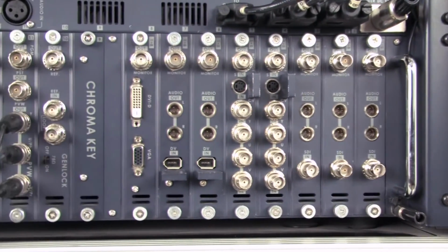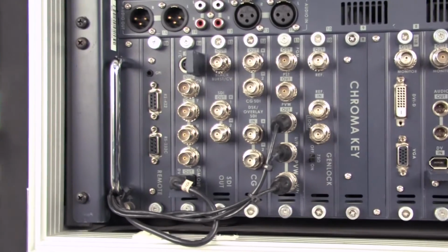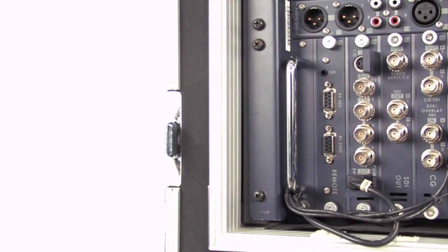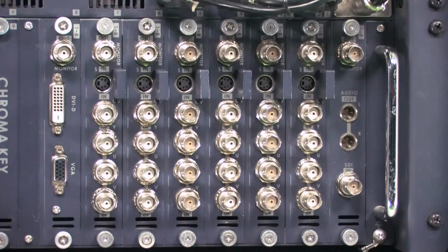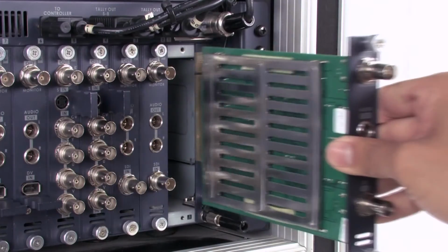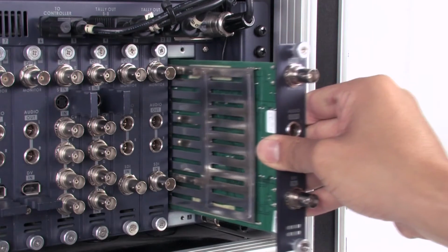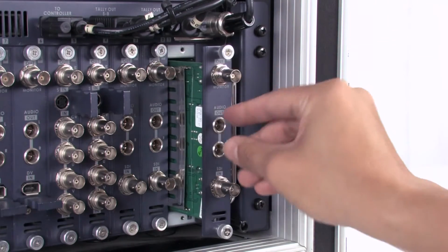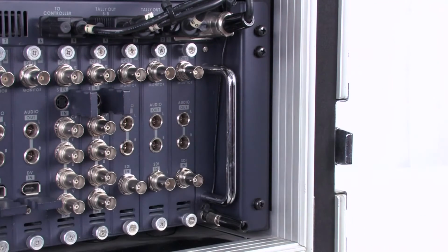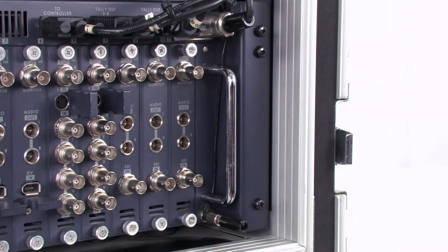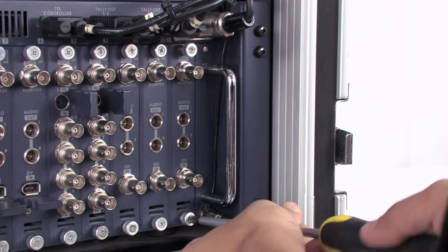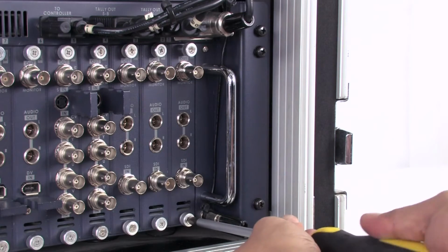All of the above input interfaces are designed to work with different makes and models of video cameras for use in different on-site environments and applications, connected to the SDI-900 main chassis. Below, we will demonstrate the assembly steps for the input interface. First, firmly insert the input card into the slot. You will hear a click sound as confirmation that the input card is securely inserted. Secure the card with upper and lower screws to complete the installation process.